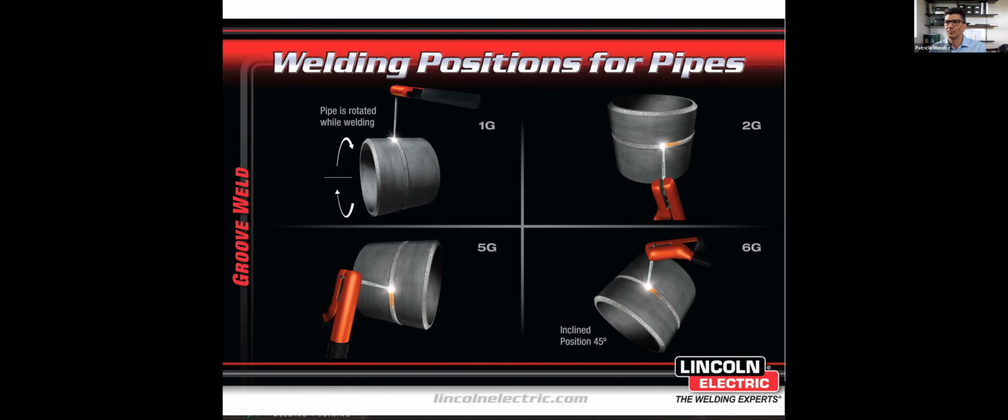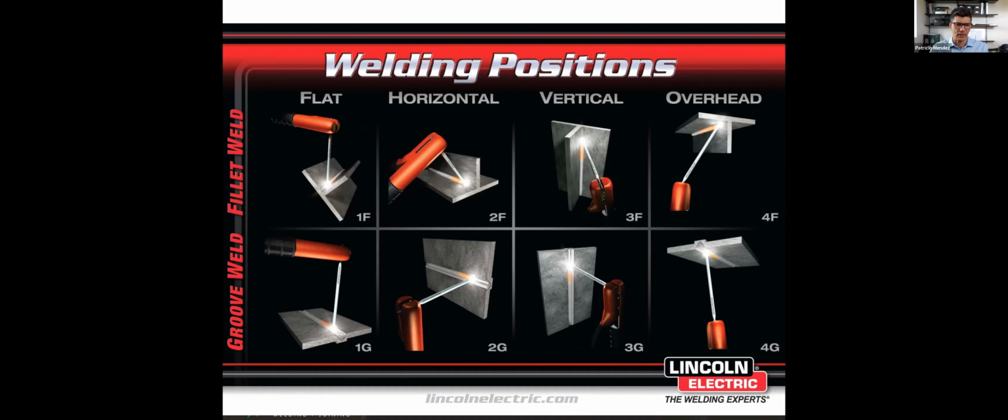I have a question: what is the difference between flat and horizontal? So let's look at this schematic for a groove here. In the case of flat, gravity is helping me, pushing the weld down and against the plate. In the case of horizontal, and I know these two terms are kind of confusing,